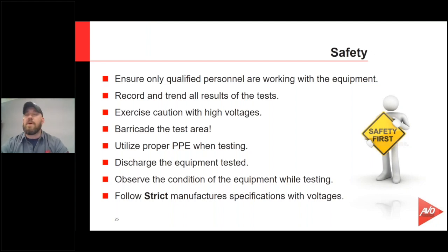These bottles could emit some sort of radiation if they do fail at some point in time. They're normally going to be at higher voltages. So if you are testing these bottles, keep them about 3 feet away from where you're at. Whenever I'm testing equipment, I like to face my apparatus that I'm connected to, but in regards to vacuum bottles, I'll turn them around and face them away from what I like to call the blast point. That way, if it does fail, it flows the other way, away from me.